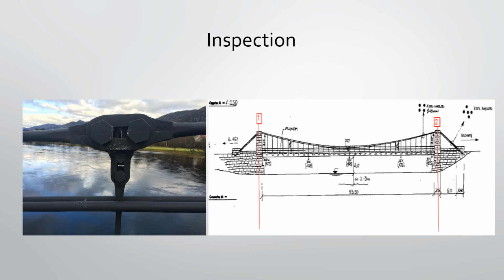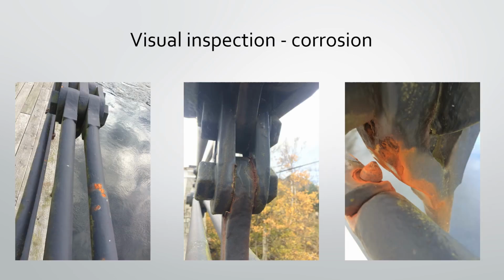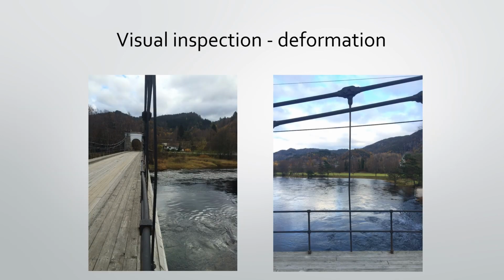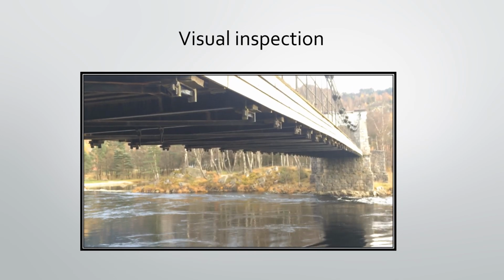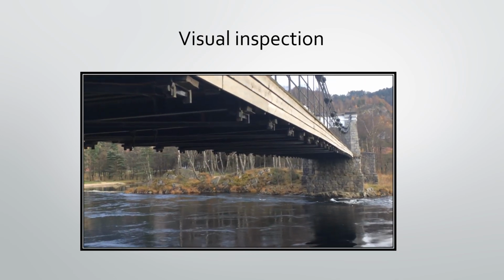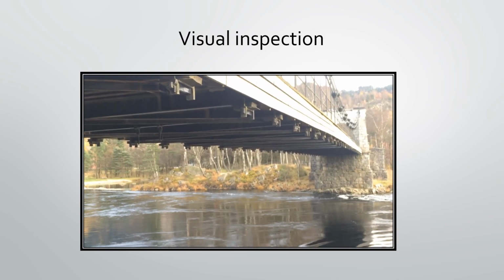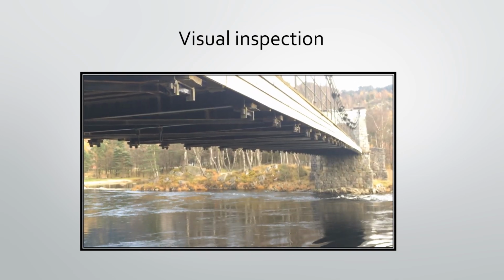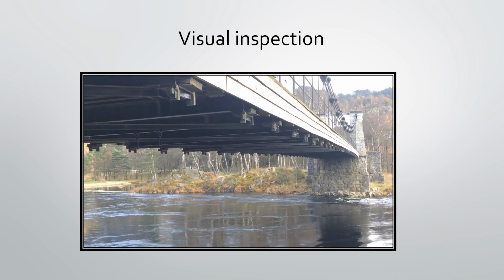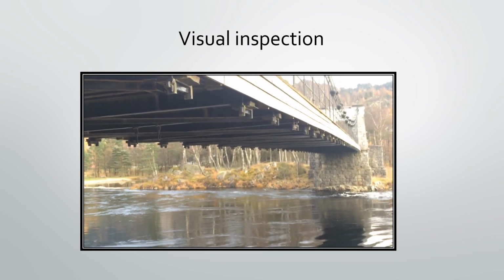The significance of any findings for the structure needs to be evaluated. The student group looking at Bakke Bridge a few years ago used visual inspection and determined some corrosion damage, in addition to some deformation of one of the structural elements. They also observed the behavior of the structure during loading, the passing of a car. If the deformation of the structure is measured with accuracy for well-known loads, this information can be very useful in checking and improving the structural analysis.